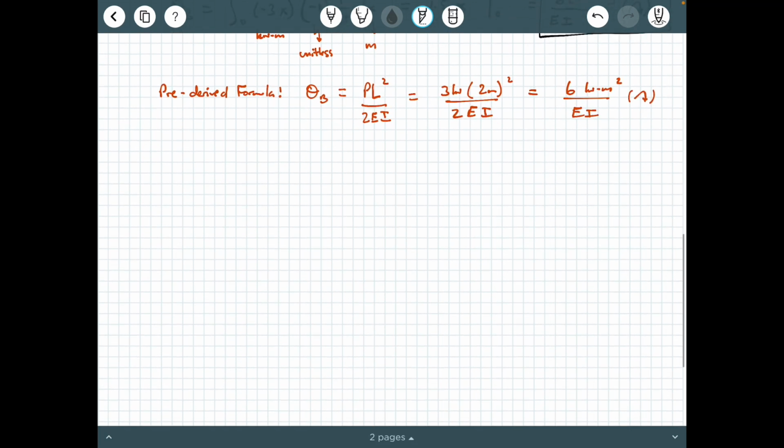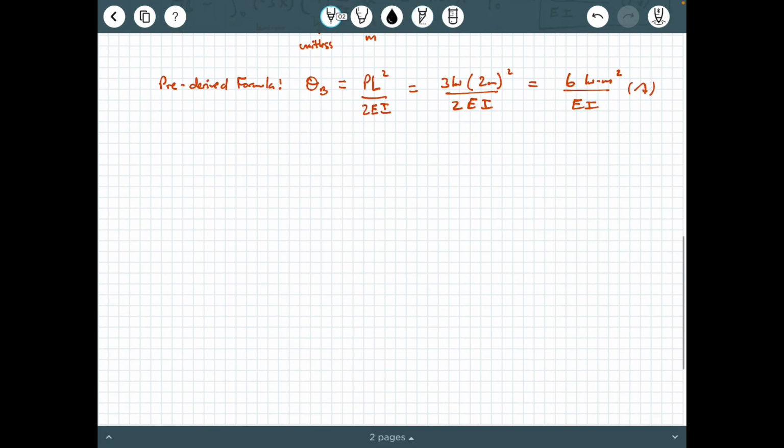So what do we do for that? All right, let's now compute the vertical displacement. Here we draw this free body diagram, and we're going to say P plus 3 kilonewtons, and this is 2 meters long. Now, we keep the real load on there. That 3 kilonewtons is the real load, and then we put a P on top of it. That's the variable load.